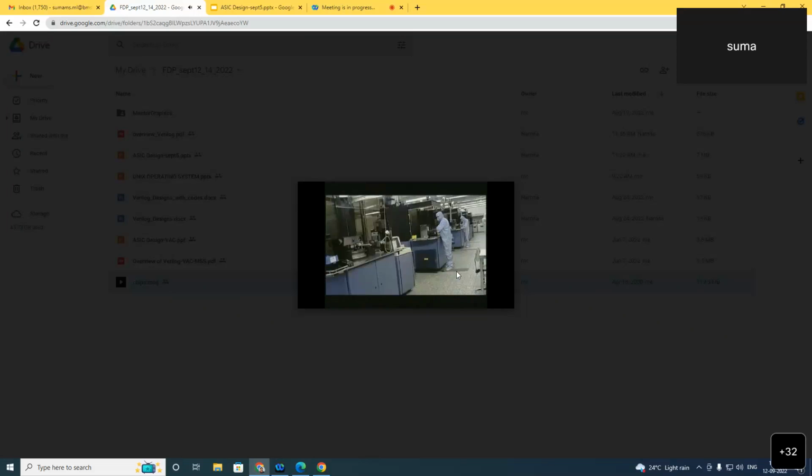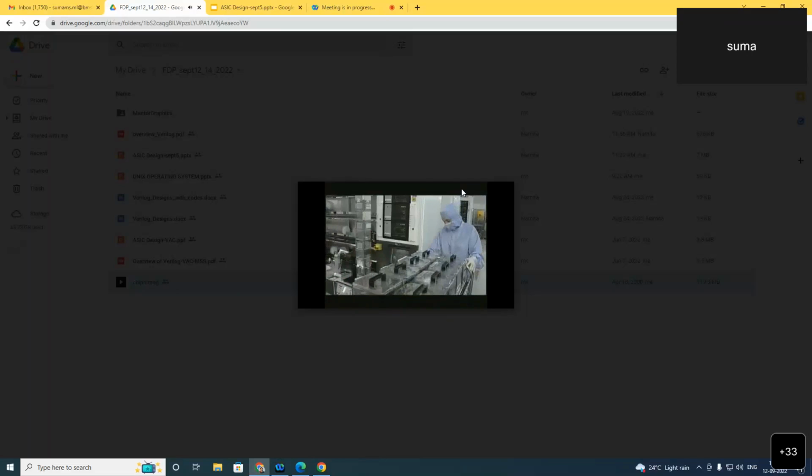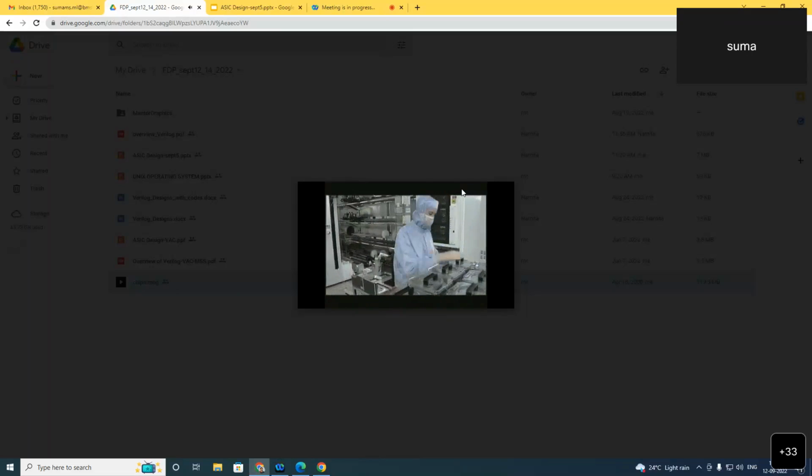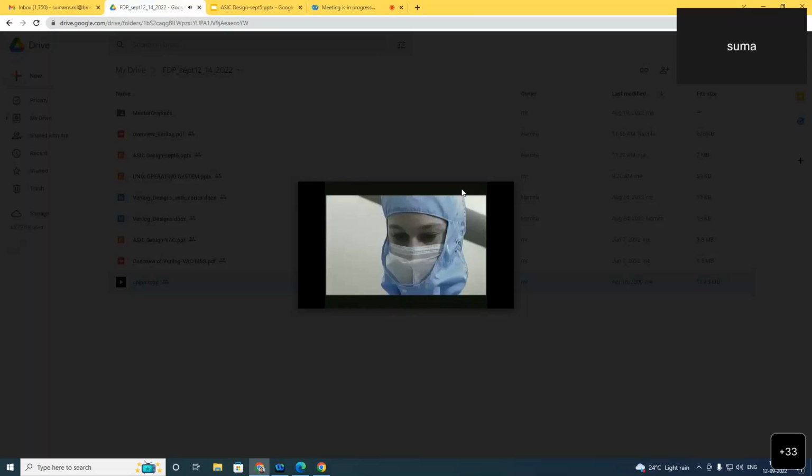The first step in the production process is as follows. In a special oven, the slices are covered by a thin layer of very pure silicon, into which the transistors and other components can be built. The slices with a monocrystalline silicon layer are placed in other ovens, where the silicon is allowed to oxidize. This insulating oxide layer can be removed at a later stage when necessary.